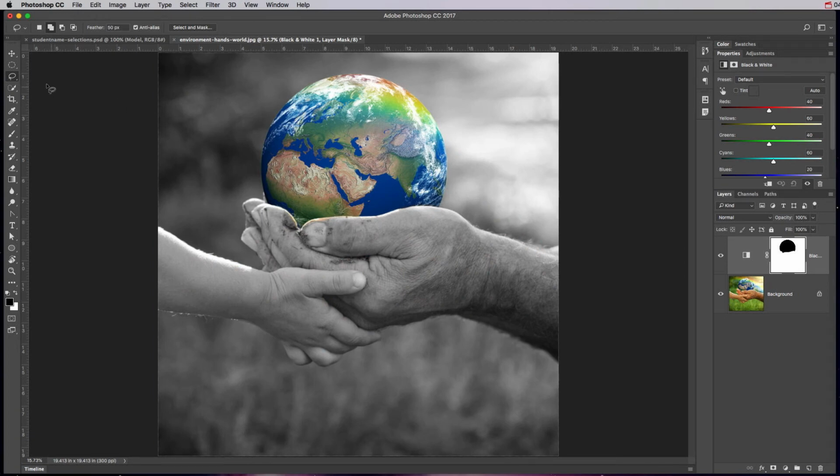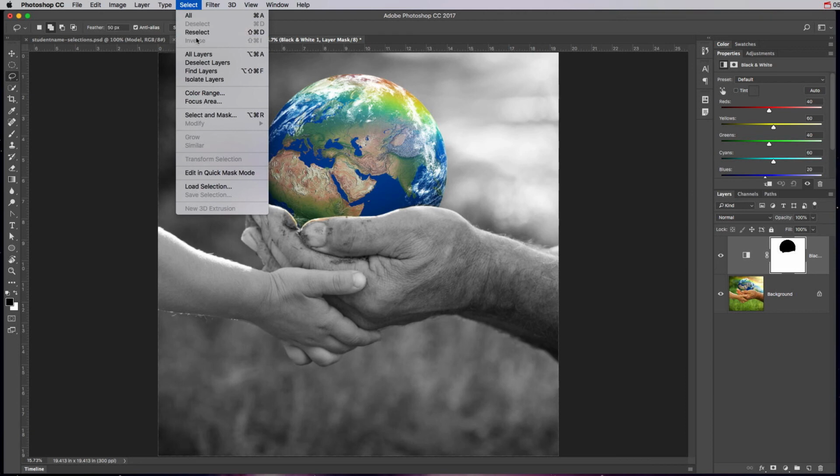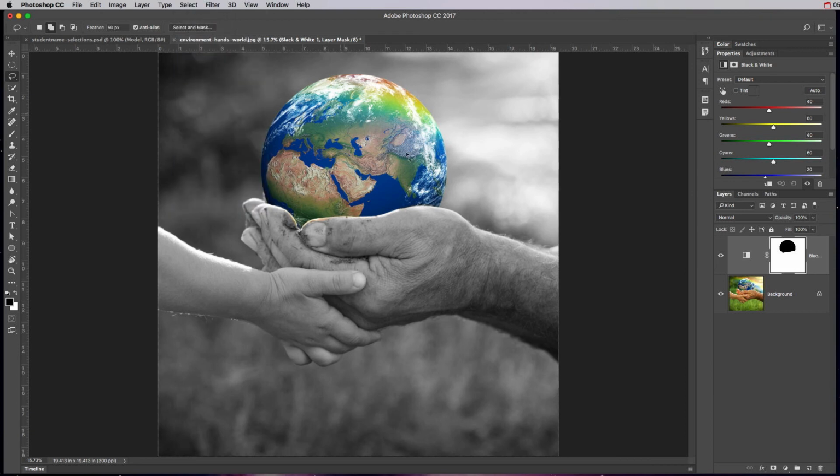So when you're using the selection tools, the basic things you need to remember: one, your three tools are going to select pixels, so you have to be on a pixel layer. You could select an empty layer, but it's not going to really do anything on an empty layer because there's no pixels to select. Two, you can add to or subtract from any of your selections. Three, you can deselect or inverse your selection. And whatever is selected is what will be affected.